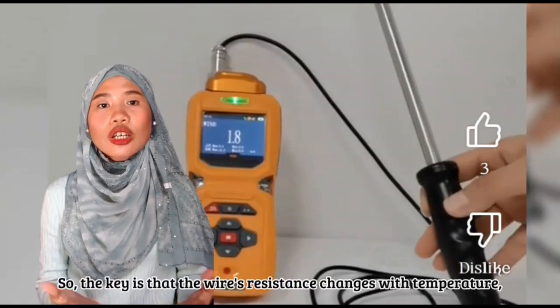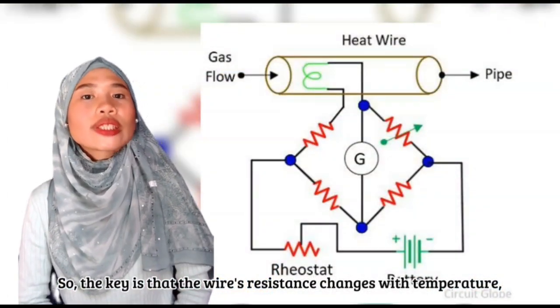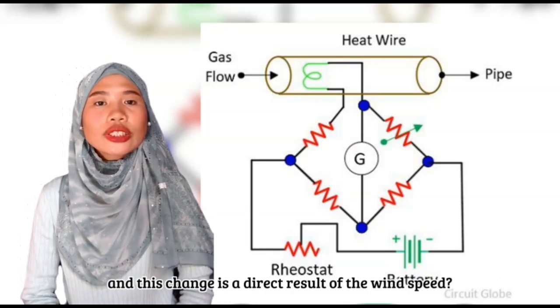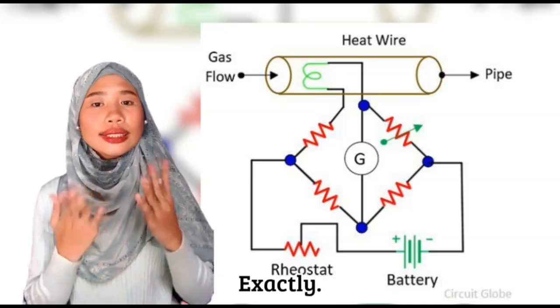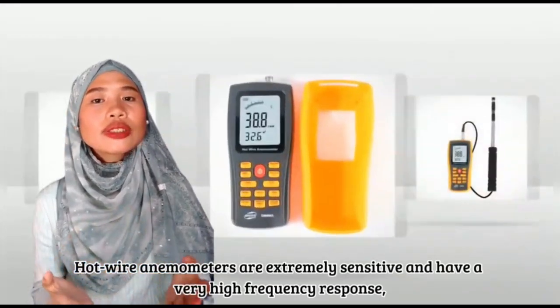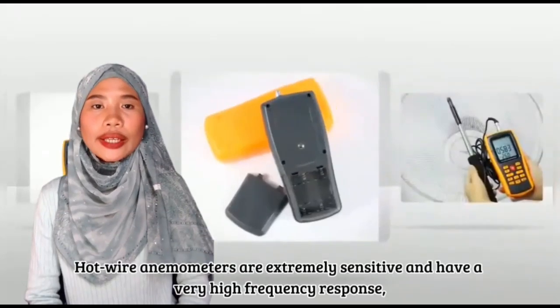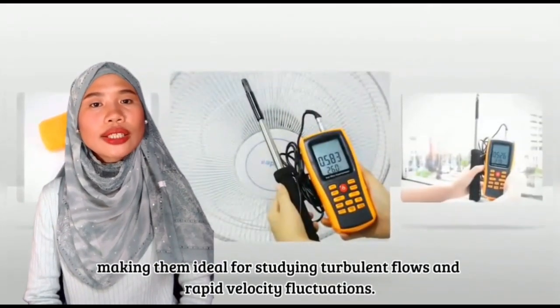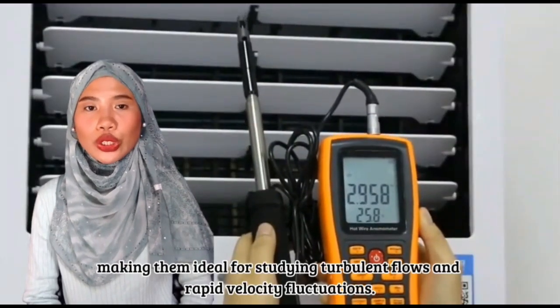That's fascinating. So, the key is that the wire's resistance changes with temperature, and this change is a direct result of wind speed. Exactly. Hot wire anemometers are extremely sensitive and have a high frequency response, making them ideal for studying turbulent flows and rapid velocity fluctuations.